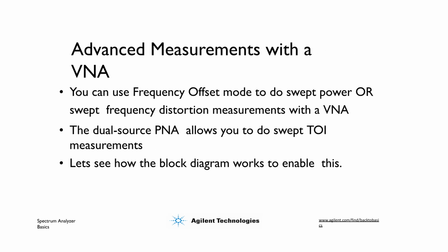Advanced measurements like swept power or swept frequency distortion can be performed with a vector network analyzer using frequency offset mode. Dual-source VNAs also allow swept two-tone intercept TOI measurements.